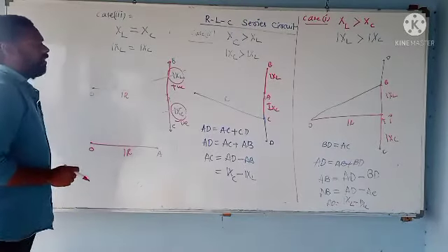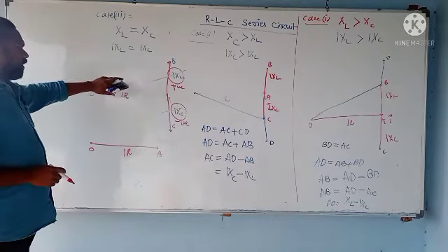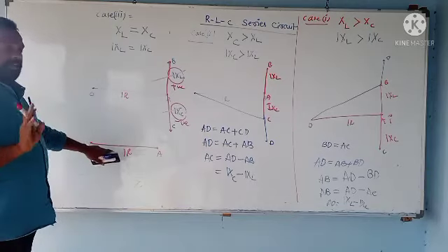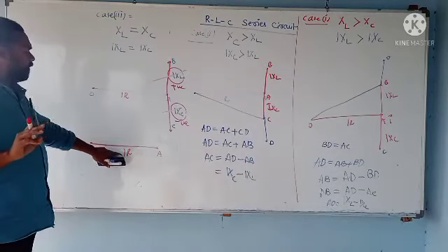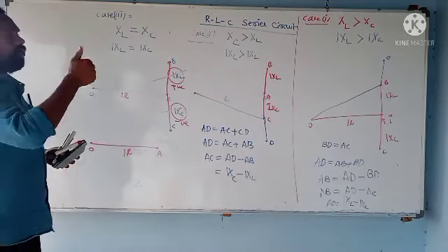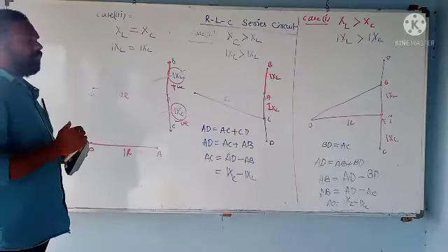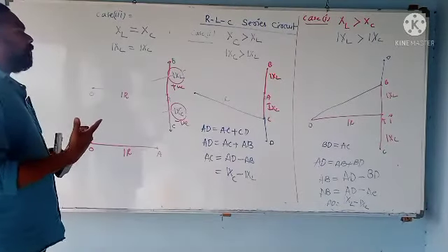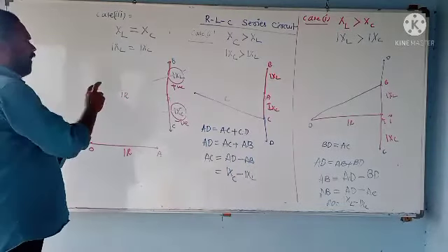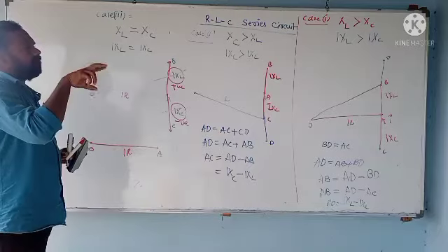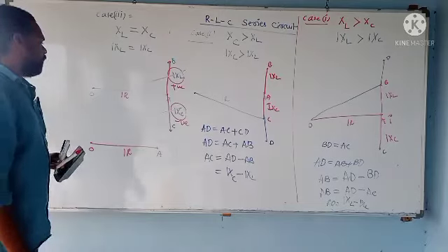The point to be analyzed here is that when the reactances offered by the inductor and capacitor are the same, those reactances cancel out each other. Finally, the leftover term is R. It means that if the inductive term is dominating the capacitive reactance, then that circuit behaves like an RL circuit. When the reactance offered by the capacitance is dominating the XL term, then that circuit behaves like an RC circuit. When XL and XC are the same, then that circuit behaves like a pure resistive network.